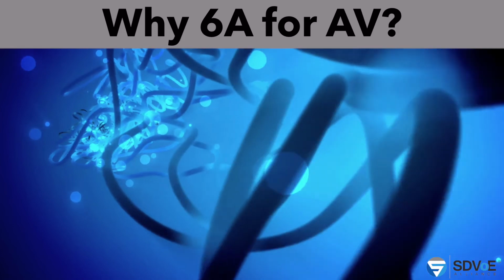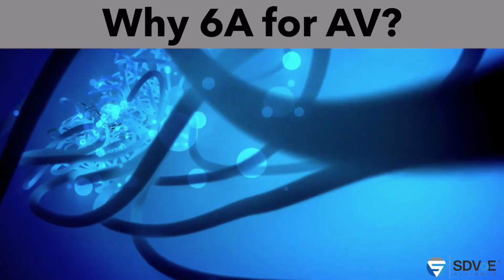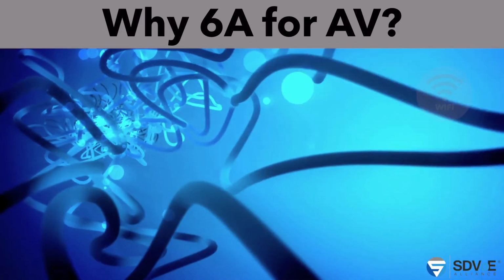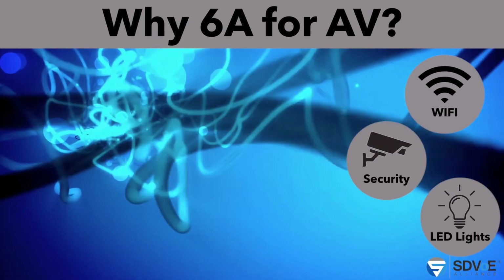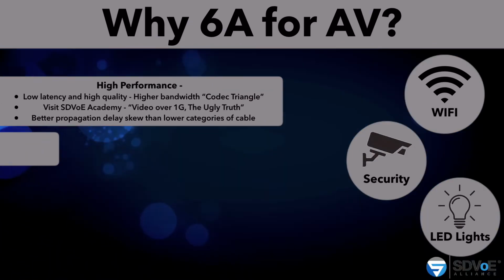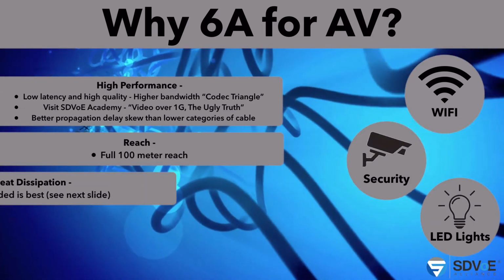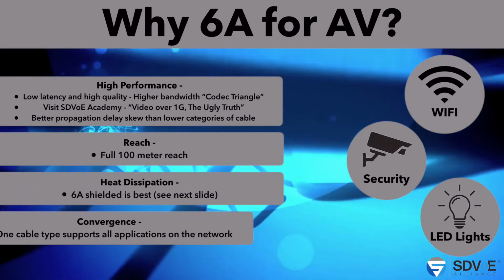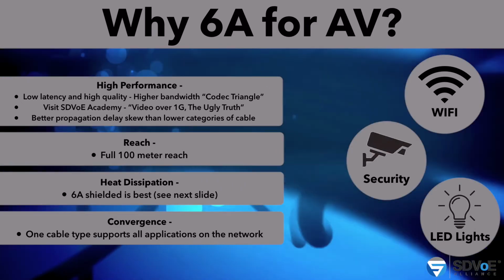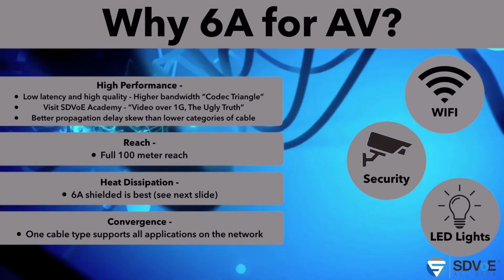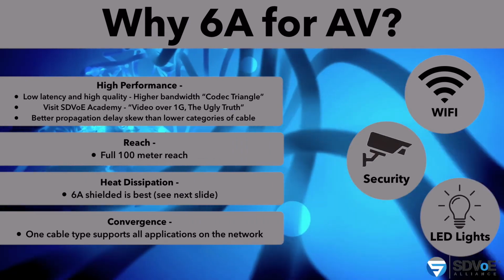So why would we use category 6A? Well, there are lots of reasons. I don't want to go into them, I'm happy to talk with anyone offline if they really want to get into it, but there's low latency, high data transfer, high speed, little delay skew. Over all of those 4 pairs, we're splitting up the data transmission, we're delivering it, and it's going to reach the end exactly as we've sent it.